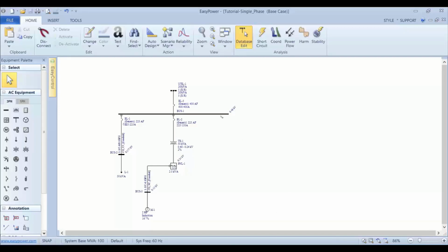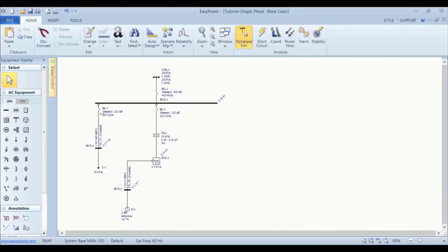The top bus is a 480 volt Y/277 volt three-phase four-wire bus with two feeders. One, a 277 volt line and neutral connection, and a second, a 480 volt line-to-line connection to a transformer with a single-phase three-wire center tap that feeds a panel and a 2 horsepower single-phase motor.